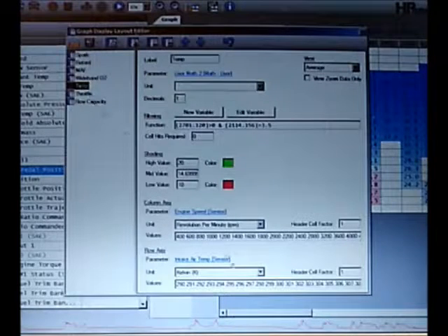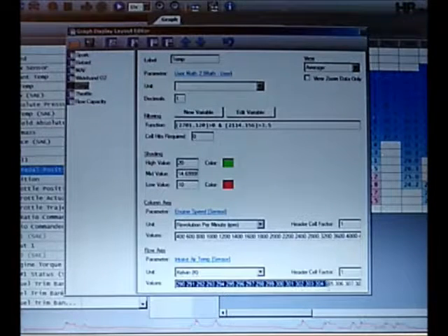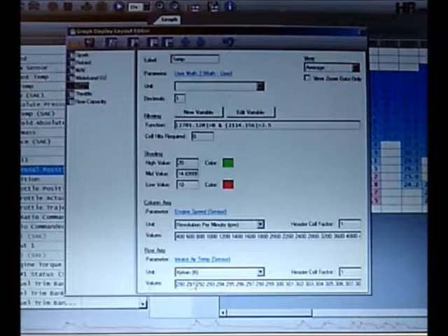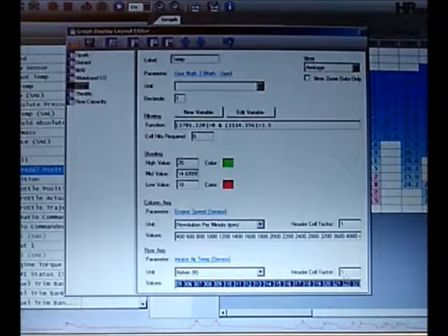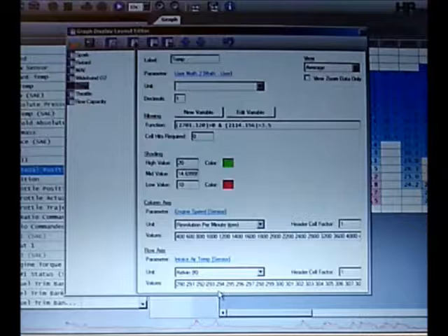And this one actually uses, in addition to engine speed, intake air temperature. The intake air temperature sensor is one of the PIDs you're going to need to log in Kelvin, and then you can type in whatever range you want. I just arbitrarily entered this range from 290 to 323. The way Kelvin works is 273 Kelvin is 0 degrees Celsius. So whatever temperature you think your intake air is going to reach.